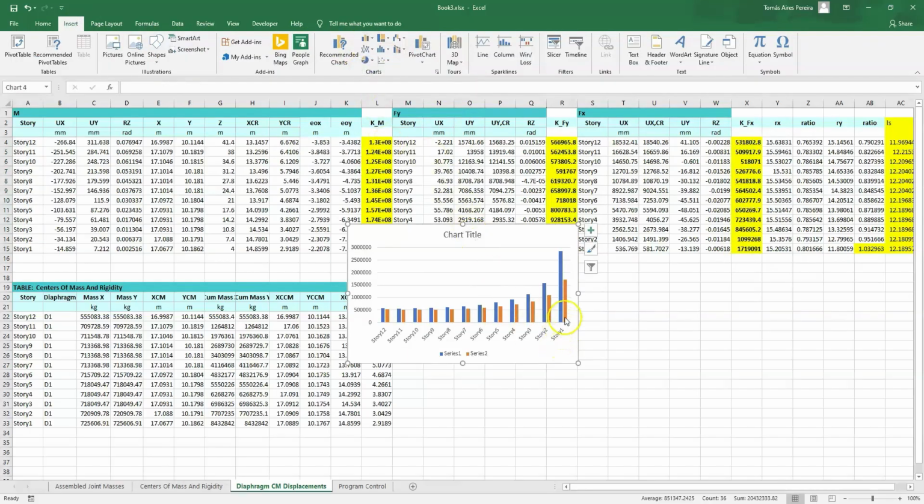We can see from right to left the floors rising in height with the two different directions shown in blue and red. And we see that we truly have continuity. That is, there are changes, as expected, because the stiffness will naturally change from the base, due to the total fixity of all structural elements, until the point where this fixity is no longer as significant and the stiffness remains more or less constant at each story.